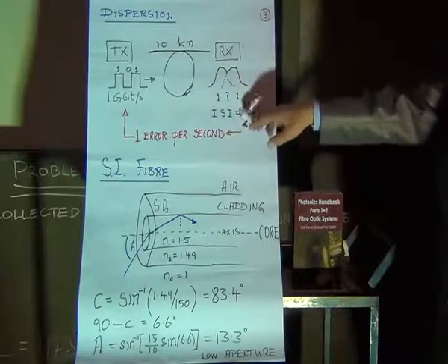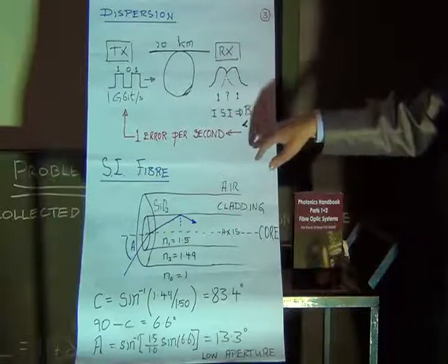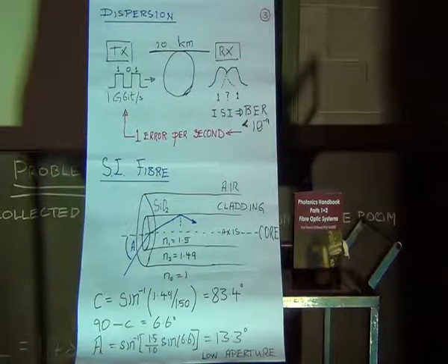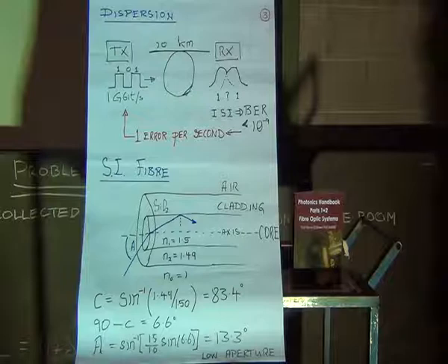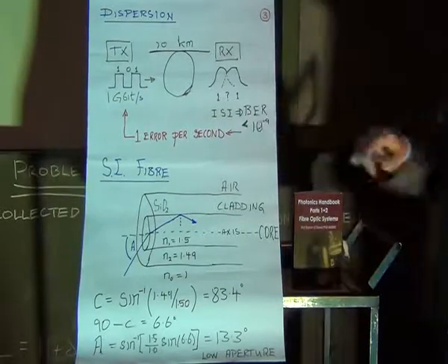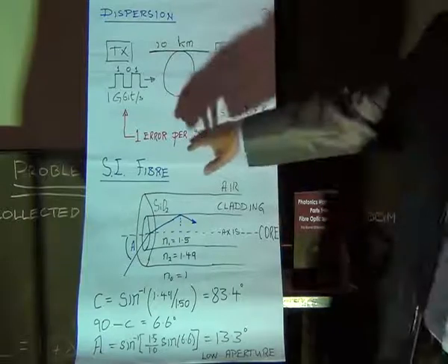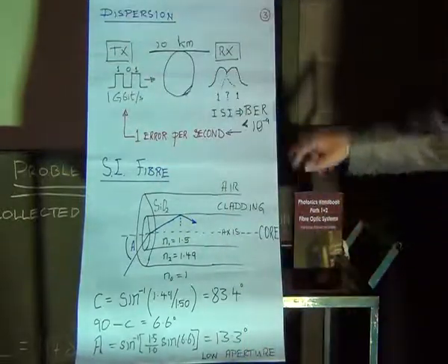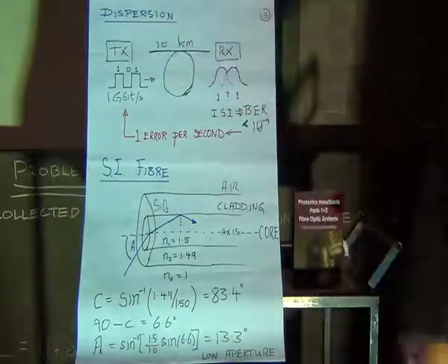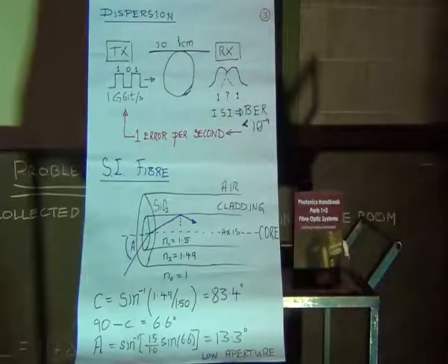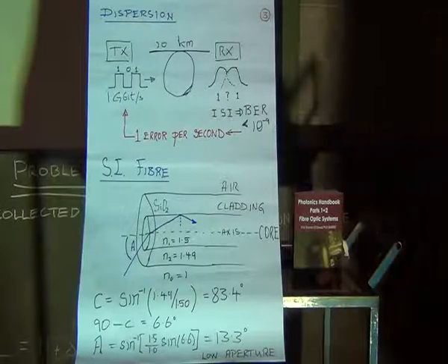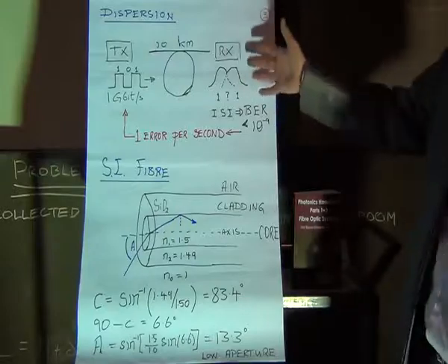It is agreed that due to this process, there should never be more than 1 error in a billion. So bit error rate must be less than 10 to the minus 9, 1 in a billion. If you look at that, when you're sending 1 billion bits per second, that means you're getting 1 error every second. So it seems like a stringent requirement, a BER of 10 to the minus 9, but it actually can be severe in certain quality situations.